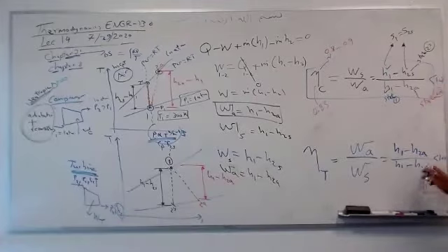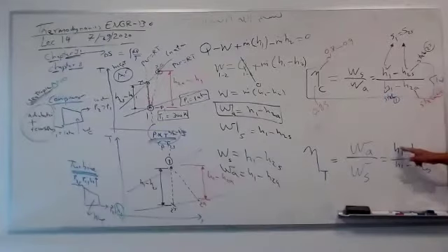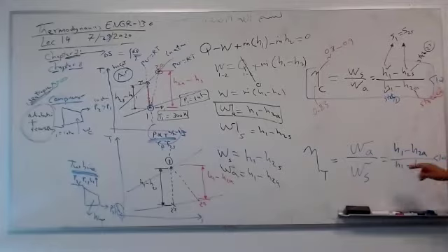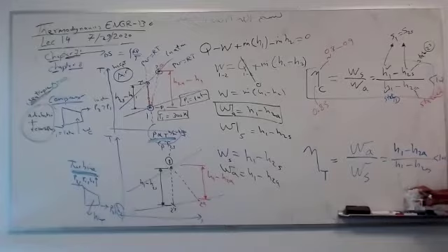Again, we have 3 states here, guys. 3 states: 1 to A to S. If you have state 1, you have 2 pieces of information, so you can find every state. For state 2A, you need 2 pieces of information. For 2S, 2 pieces of information. But still, we have something common between 1 and 2S, which is that S is equal, delta S equals 0, or isentropic.